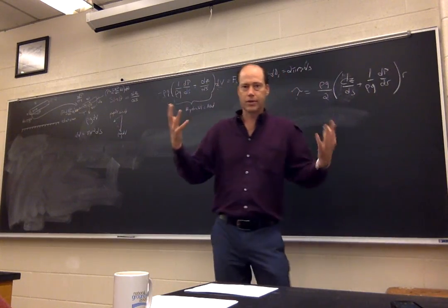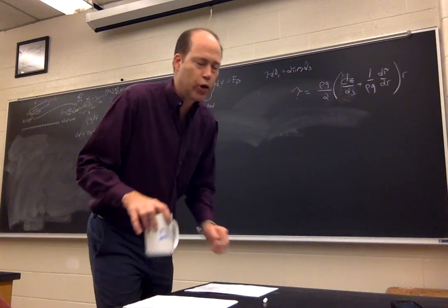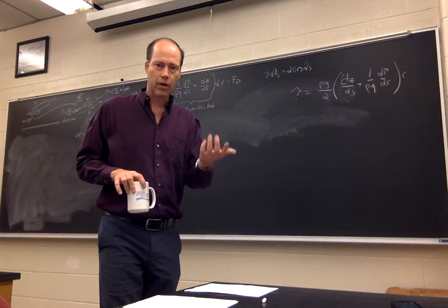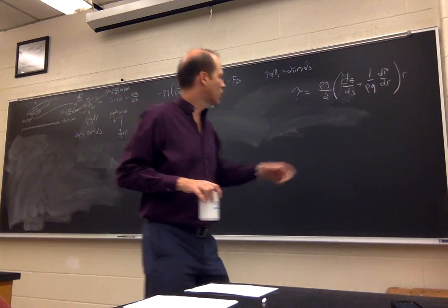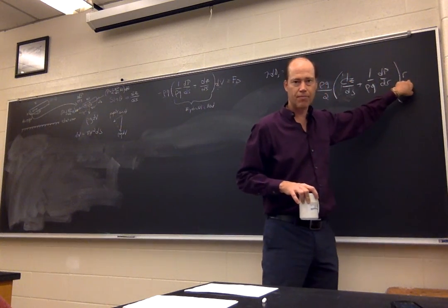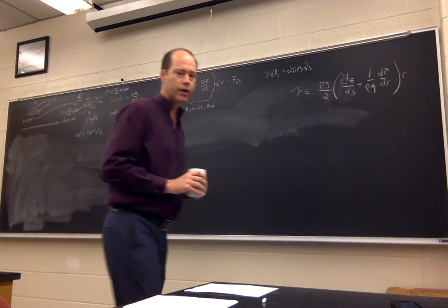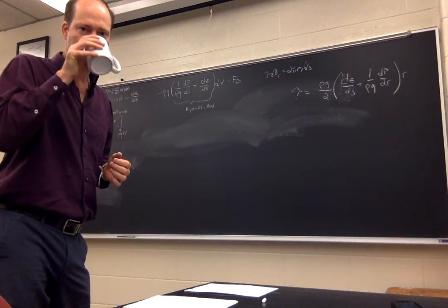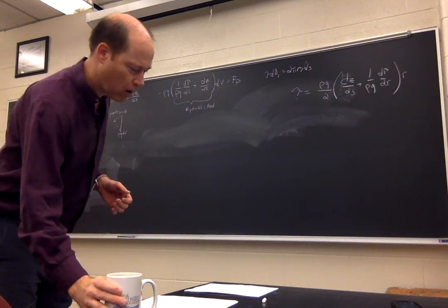And that r is very valuable because that's the size of our control volume. So, type of fluid, hydraulic head, size of pipe. Those are what control the shear stress on our system.